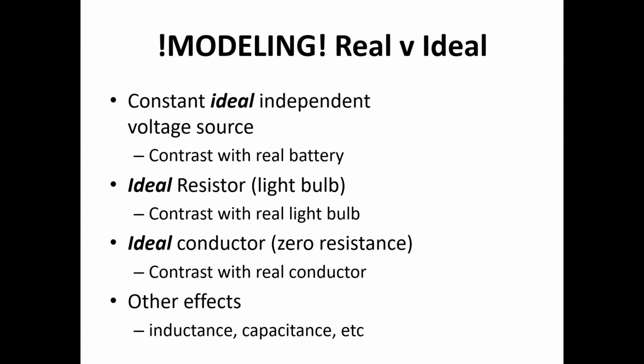Think about a 2-conductor wire. It's a little bit like a capacitor. You've got 2 metal things next to each other. That's how a capacitor is built. So a wire has a little bit of capacitance. Also, a long wire is going to have a magnetic field associated with it, so the magnetic field in one wire is going to permeate the second wire and affect that.